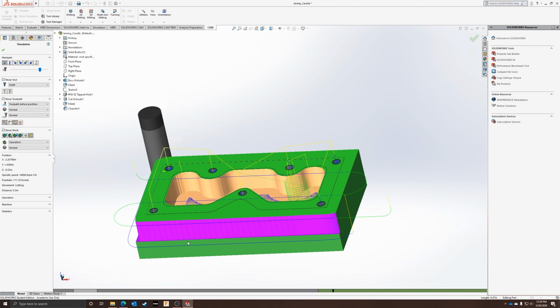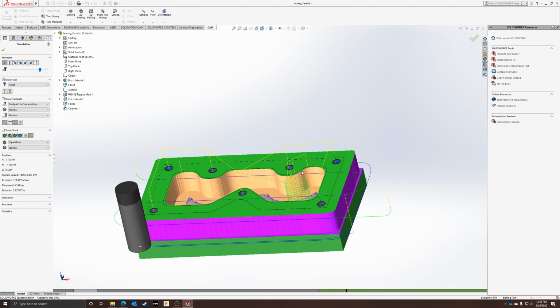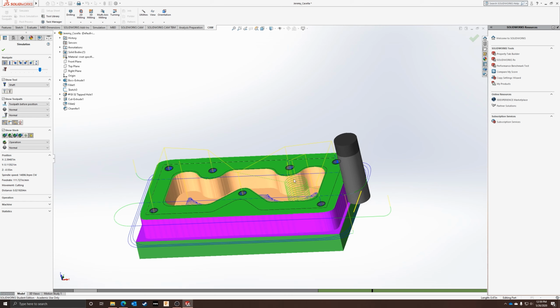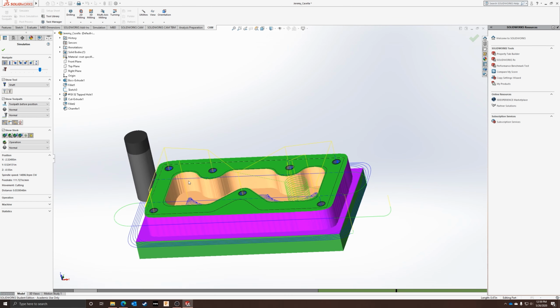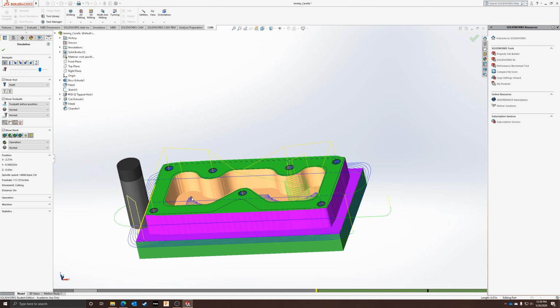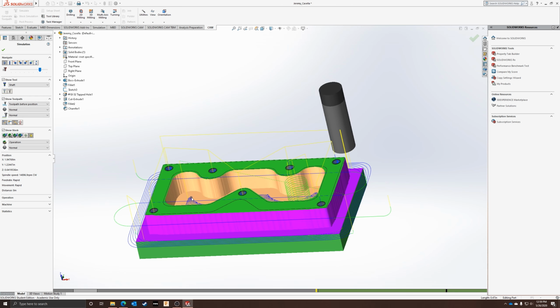You'll notice something peculiar about the inside. There's these really large corner radiuses, and it's kind of sketching me out, right? Because if I take a tool and try to move along this line, that's going to be a really sudden and intense engagement. If I reach that, it might snap my tool. Well, let's think about why that is while we see the rest of it working on the outside. So it's going as fast as it can. Okay. And it's going to get rid of that pocket there.